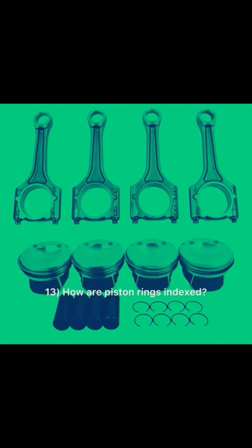15. How do manufacturers align the connecting rod caps? Fracture, sintered metal. Dowel. Shoulder on rod bolt. 16. What is the purpose of the connecting rod spit holes? Oil the cylinder wall on major thrust side. 17. How should you remove piston rings? Use piston ring expanders for compression rings. Spiral off oil control rings.